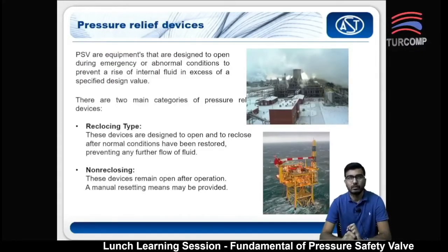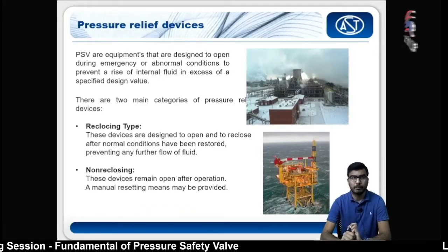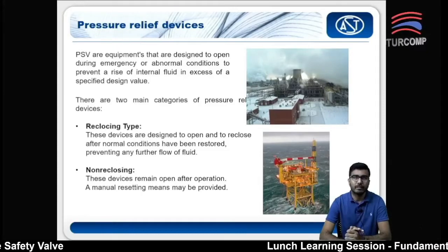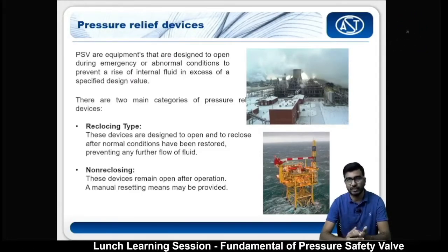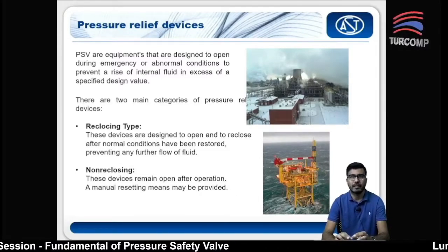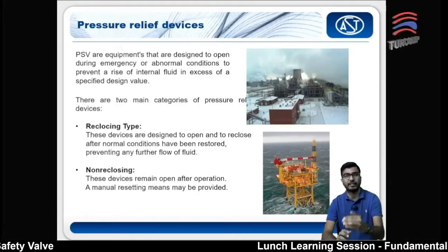Okay, so the pressure relief device. PSV or PRV are basically equipment that are designed to open during an emergency or abnormal condition to prevent a rise of internal fluid pressure in excess of a specified design value. This is actually your set pressure.